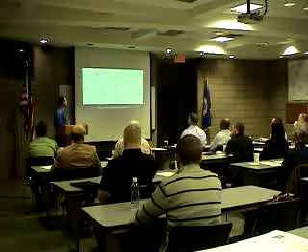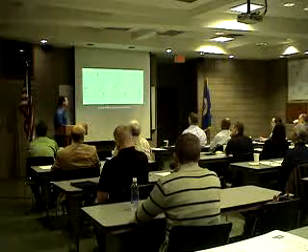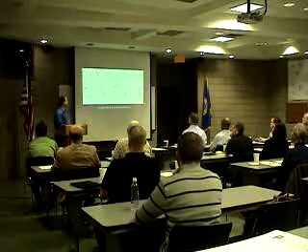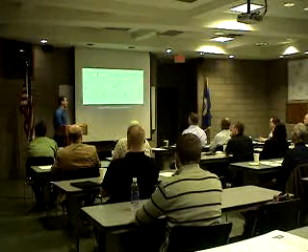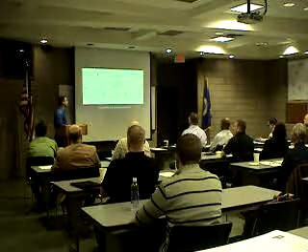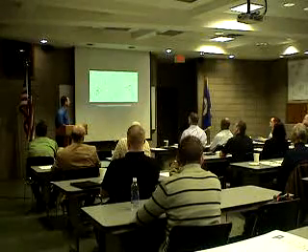As you can see, this here is a pretty standard office layout, one receptacle on each wall, plus a quadruplex receptacle for data. And then this is a conference room, has a junction box for power underneath the conference room table, and then again an outlet on each wall for general use and a data outlet, which is quadruplex receptacle.